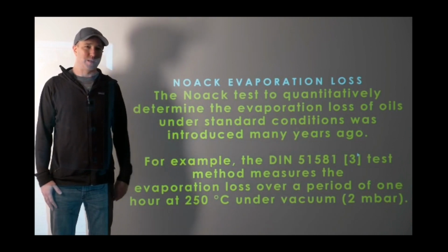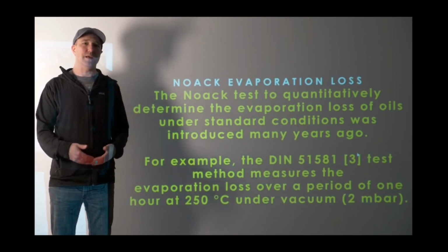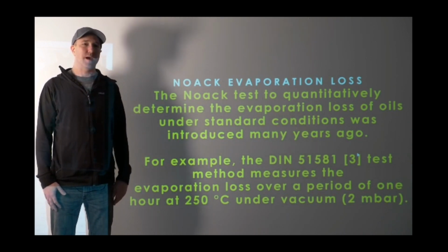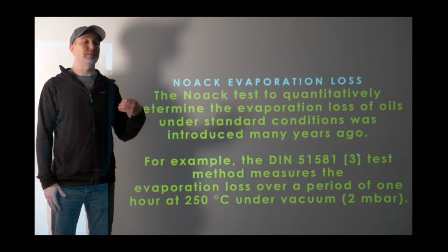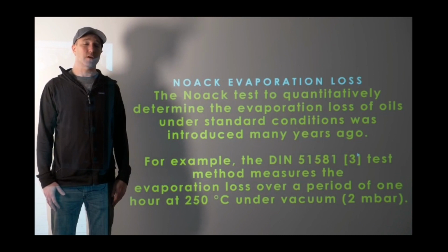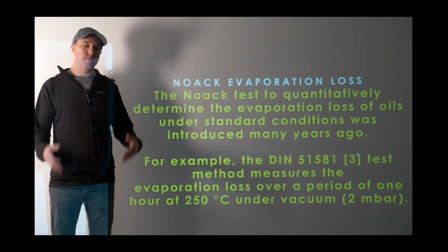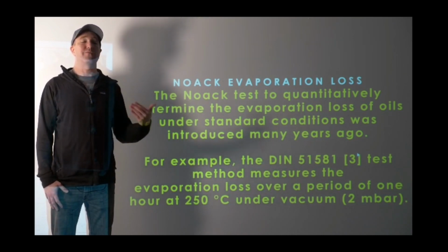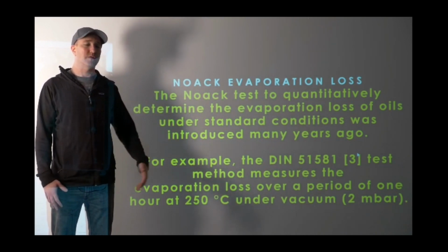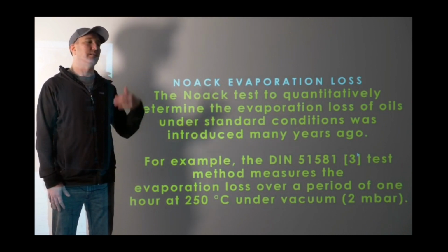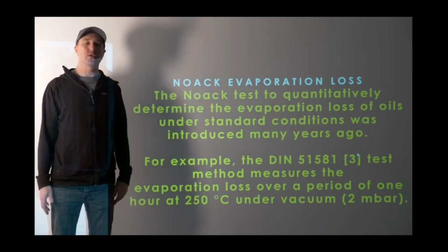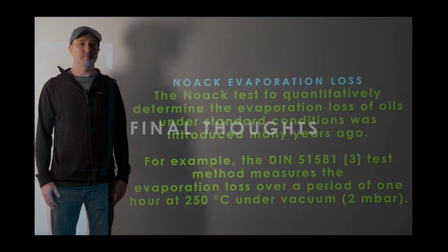Now, here's the other problem. As cars move to 0W20, 0W30, or even thinner oils that are coming out, most of those oils have over 7% volatility. That's because they're thinner. So if you're really concerned about this, specifically if you have a turbocharged direct injected car, then you might want to consider a 5W or 10W or a heavier weight oil, because statistically, based on my research, most of those oils have a lower volatility rate, less evaporation, and it could help prevent some of these issues. Do your research on it though, don't take my word.